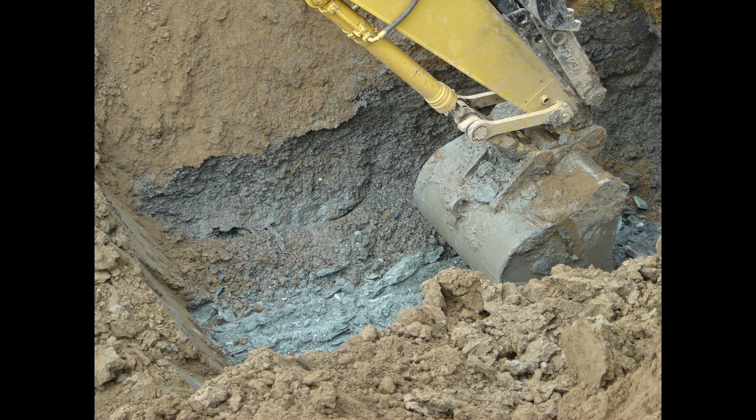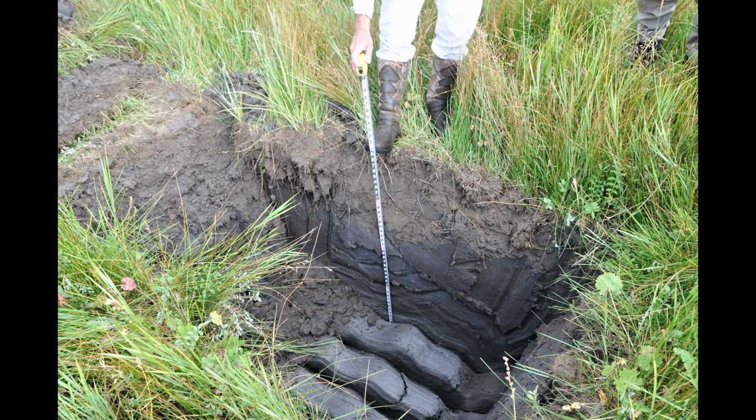Continue digging to see if there's a thick layer of clay and an impermeable layer of rock near the bottom of the hole. In this photo you see there is an impermeable layer of rock in the bottom of the hole, and this will be a great foundation for the groundwater dam. There's a thick layer of clay in the bottom of this deep test hole. It will also serve as an excellent foundation for the groundwater dam.